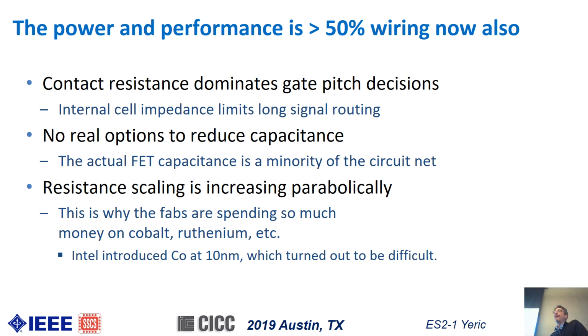And there really is not any good story in the interconnect. There's obviously a fundamental limit in capacitance, in the permittivity of a vacuum. There are limits to resistances of materials. If you've noticed, Intel had a huge problem with 10 nanometer, getting 10 nanometer out the door. That involved a switch from copper to cobalt. And that was for some very modest improvement in resistance and some improvement in electromigration. Very modest, but there's no other options.